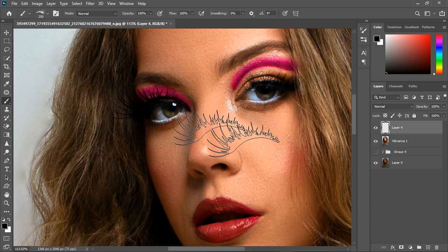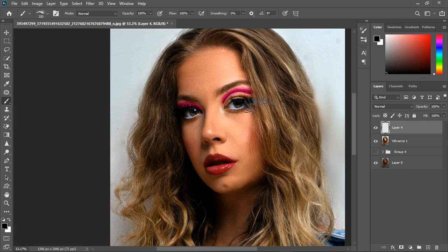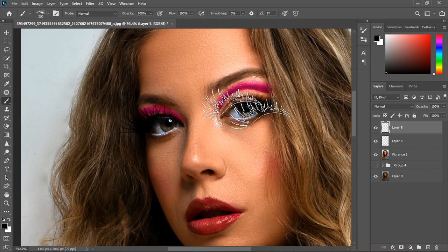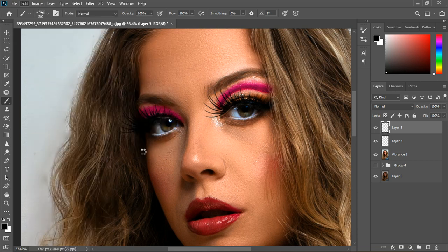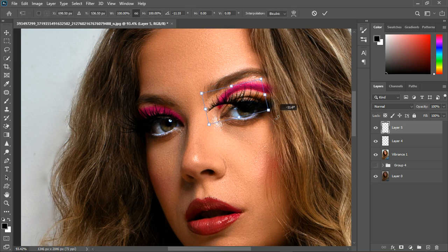one. Okay, and also I'm going to do this for this one. Let's create another layer, and just click on it like this. Now it's on the wrong direction, right? Yes, just go to Edit, Transform, and Flip Horizontal, and it's going to flip it horizontally, and we can position by rotating and dragging and placing it in the right part.